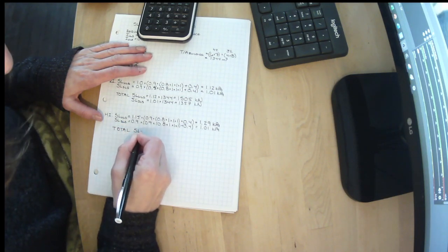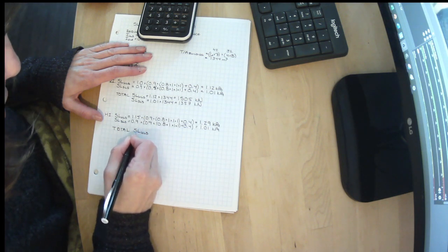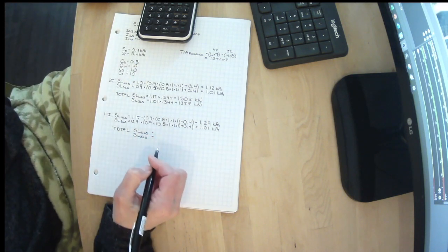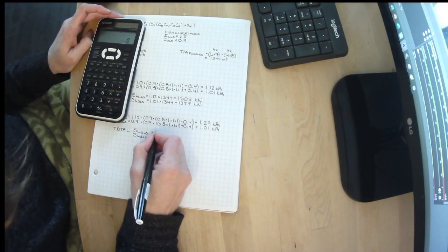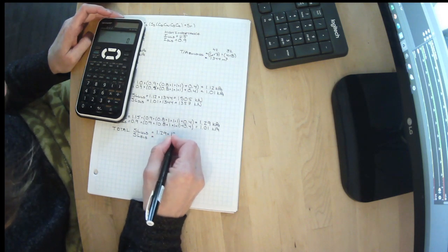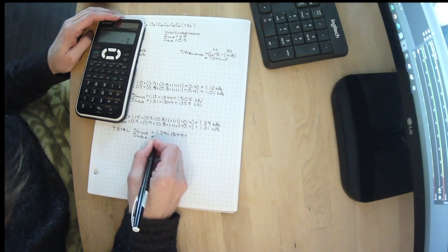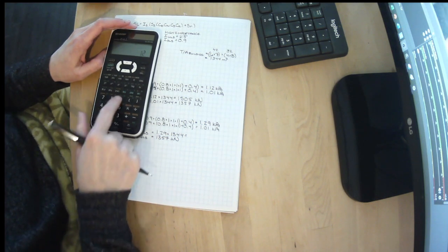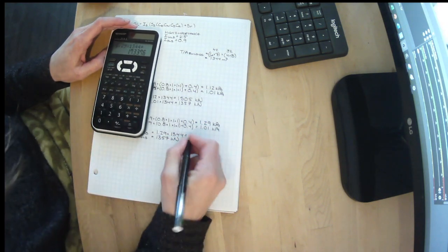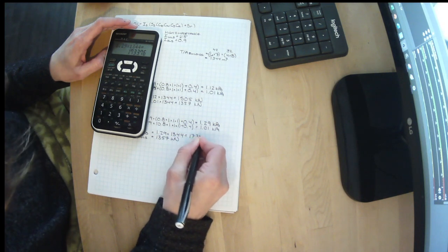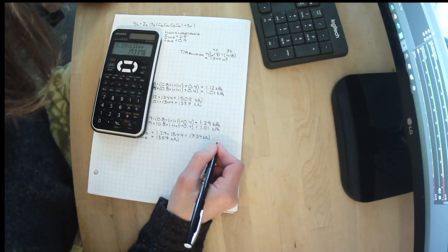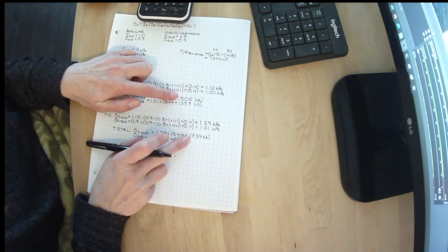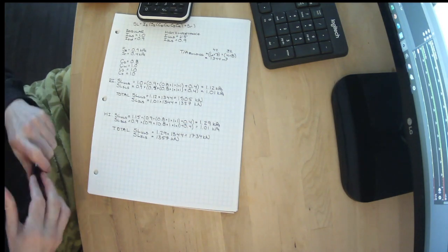And so just to be thorough here, for the high importance version of the building, we would have 1.29 times 1,344. And then this would be the same. 1.29 times 1,344. Or 1,734 kilonewtons. So you can see that we increase the amount of load on the building by making it high importance.